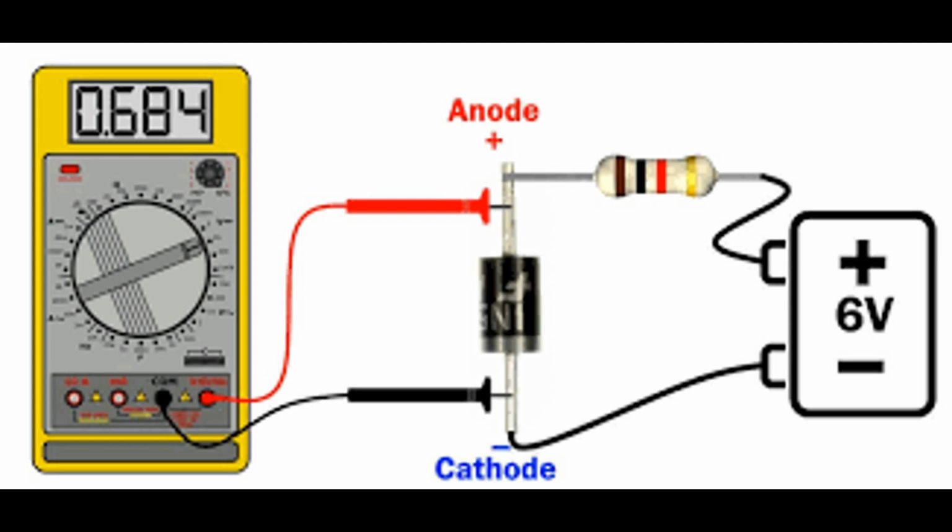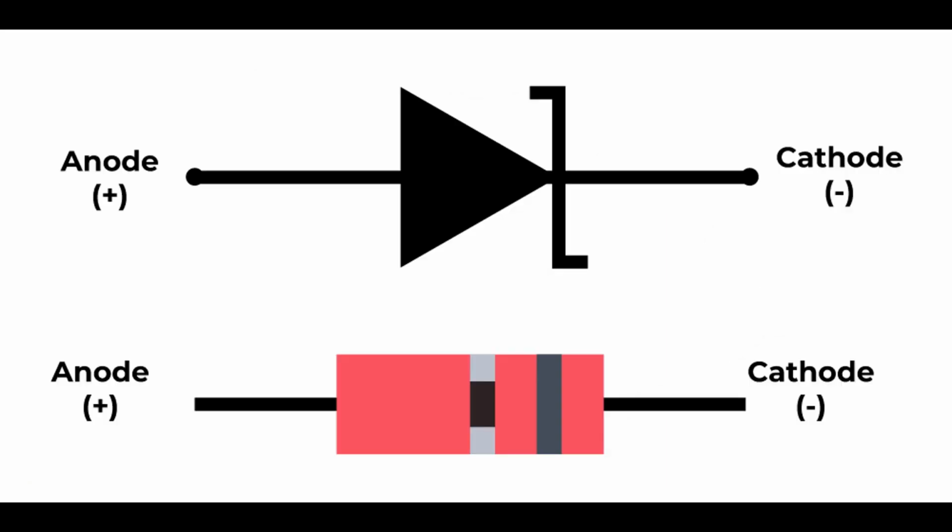There are several methods to achieve voltage shifting, and the choice of technique depends on the specific application and requirements. Some common methods for voltage shifting include voltage divider. A voltage divider circuit consists of two resistors in series connected across the source voltage. The output voltage is taken from the junction between the two resistors, which can be adjusted to provide the desired voltage level.